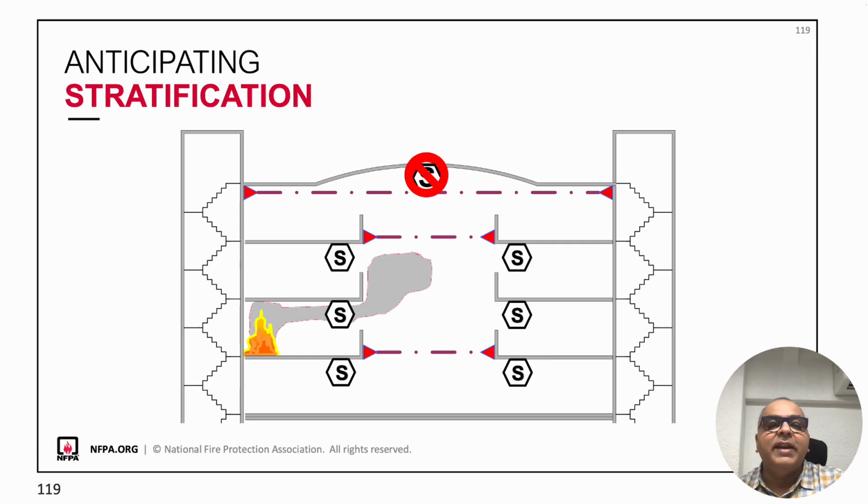Now this is a different scenario. The fire is located at one level above the ground floor. Smoke spreads sideways at the level instead of rising upward. Only a local smoke layer forms around the fire origin. The ceiling smoke detectors still do not receive the smoke. The detectors positioned lower on the intermediate floors are expected to activate while the topmost detector still remains ineffective.